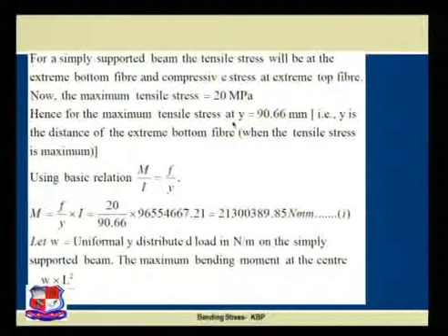As it is the bottom fiber, I have to use YB, that is 90.66, the distance of the extreme bottom fiber, where the tensile stress is maximum.